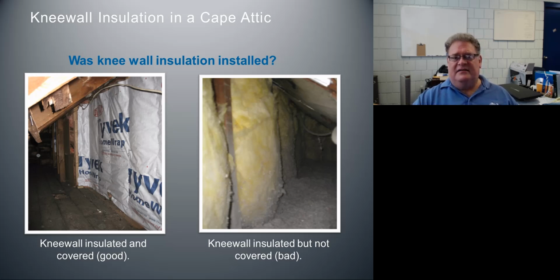As it drives heat into that insulation, it is going to make the insulation act like it's not nearly as thick as it is. So if we have 3.5 inches of installed insulation before it's all said and done, that stuff may only be acting like there's 1 inch of insulation there. The other problem is that here is the end of the stud. Let me try and draw this a little bit better. Here's the end of the stud, and look how much we have exposed of that stud. So this is a case of poor workmanship as well. If our folks installed this, we need to have something done about that.